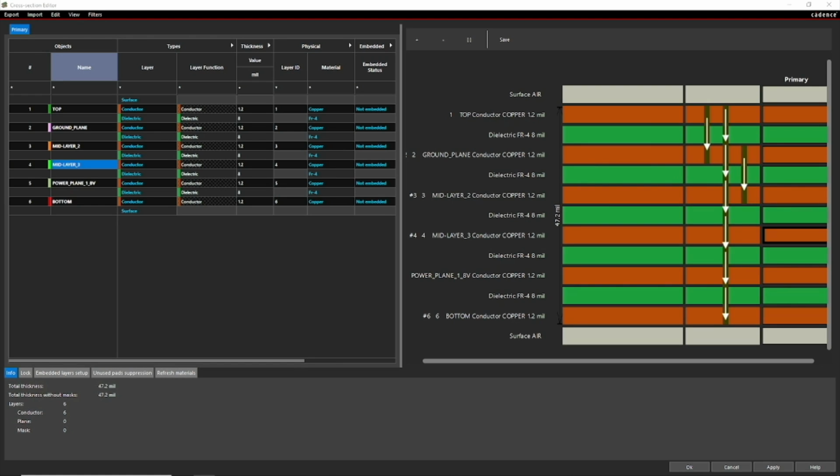The trace is placed underneath or adjacent to the ground plane or layer 2. This traps any stray EMI waves and protects the top layer traces from crosstalk and coupling that could be caused by the internal signals. This also blocks outside signals from penetrating these more sensitive high-speed traces.